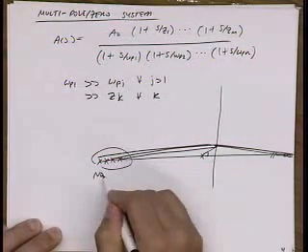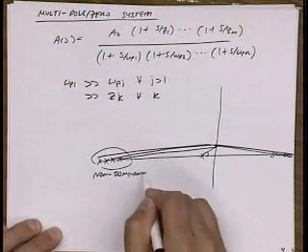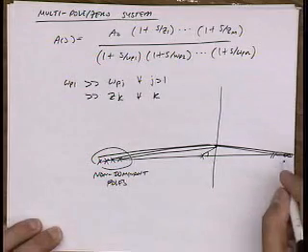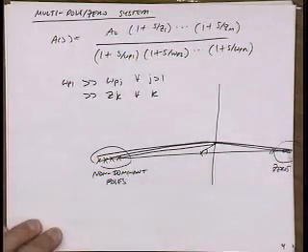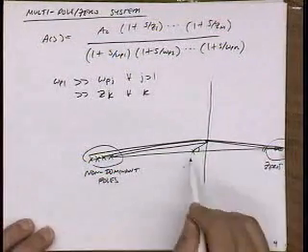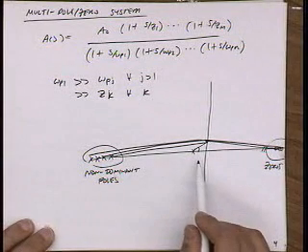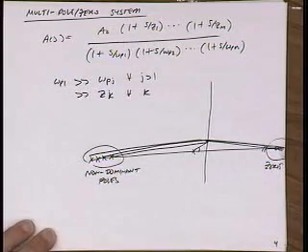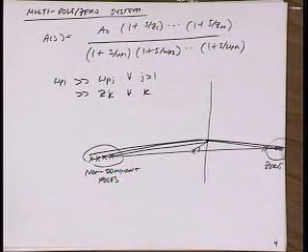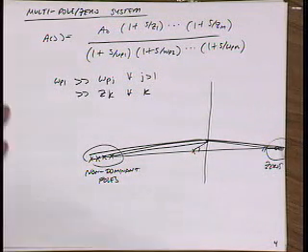So these are my non-dominant poles. These are my zeros. And I'm assuming all zeros are sufficiently high frequency that P over Z is basically much less than 1. Okay? So the claim is that these really don't matter. And of course you can work out the equations and see that they don't matter. But what's a nice intuitive, just graphical way of understanding that? Okay. Yeah, I mean, the angle is about 90 degrees, so yeah, very good, right?